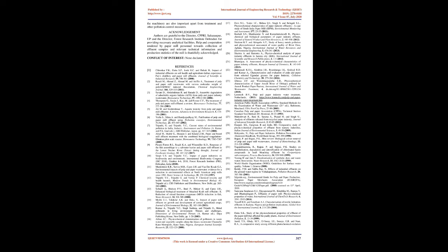As an important characteristic, turbidity of effluent is due to the presence of insoluble matters, soluble colored compounds, and plankton, which is measured either as a reduction in the intensity of transmitted light or as an increase in the intensity of scattered light. Effluents from C, E, CB, and CE units exhibited mean values of turbidity as 121.22 ± 2.62, 149.22 ± 1.75, 113.23 ± 1.46 and 481.22 ± 2.61 NTU respectively. Highest turbidity was observed for effluents from CE unit, whereas C unit effluents showed the lowest turbidity, Table 1.